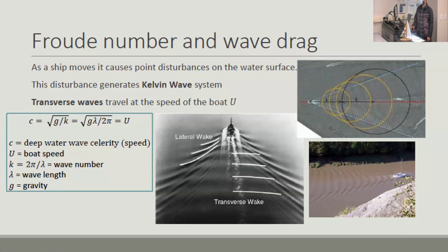Okay, they create resistance. In what way? It's not frictional resistance anymore. The waves are not rubbing up against the hull. So how do they contribute to resistance? What does it take to generate these waves? Energy.